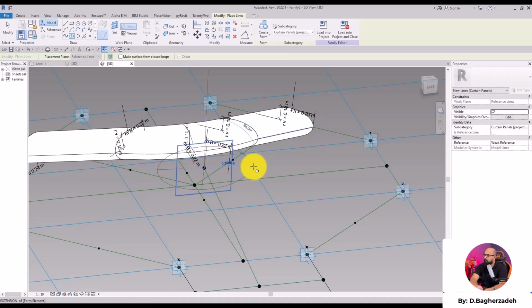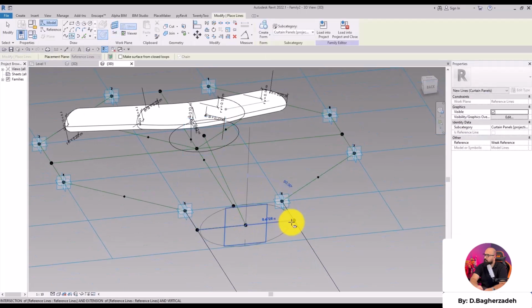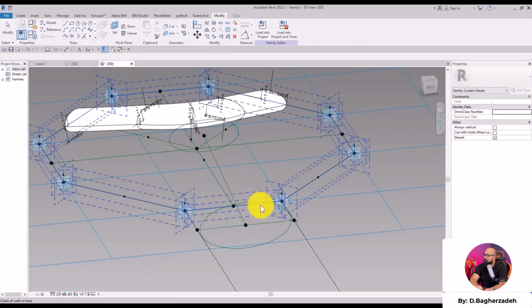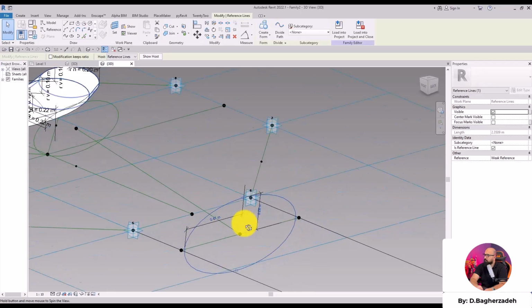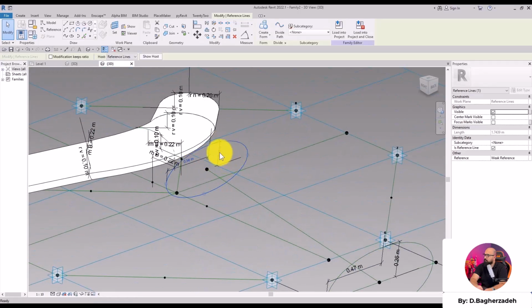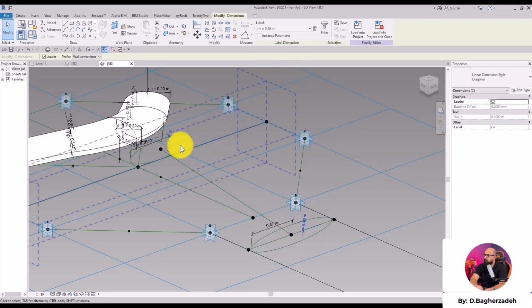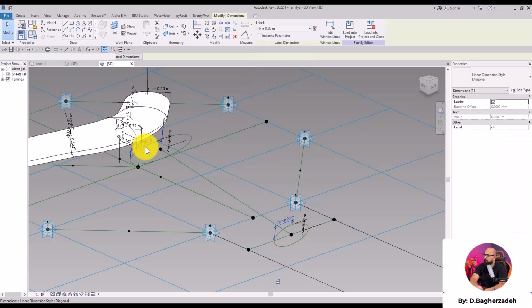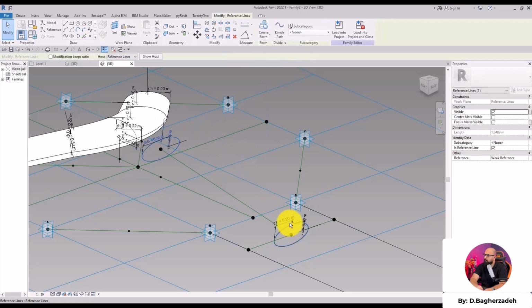Okay, this is crooked. Let's do it again. All right. And then we need another ellipse, this time here. All right, good. Now, select the ellipses and convert them into references. Then we need to set the radiuses, talking about both horizontal and vertical radiuses. Now, for these two, we can actually go with the RV parameter. And then for the horizontal ones, this one would be RH. And for this one, which is actually larger, RHB. And the end result will be this.